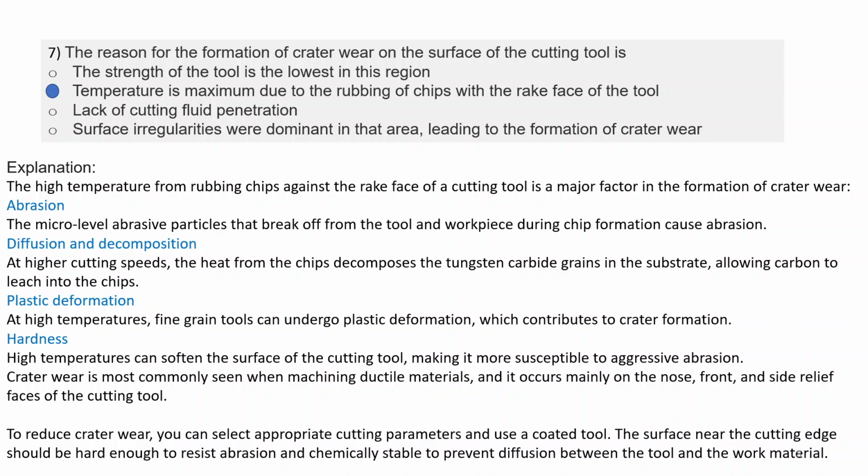Next is hardness. High temperatures can soften the surface of the cutting tool, making it more susceptible to aggressive abrasion. Crater wear is most commonly seen when machining ductile materials, and it occurs mainly on the nose, front and side relief faces of the cutting tool.